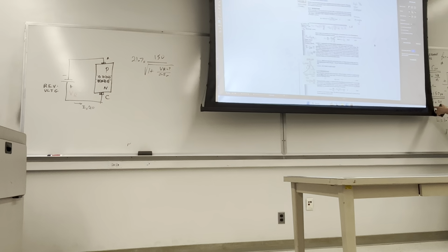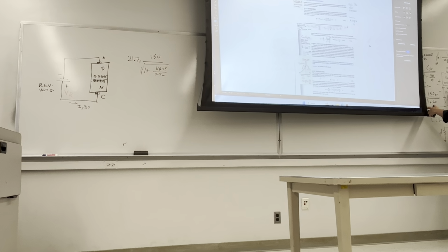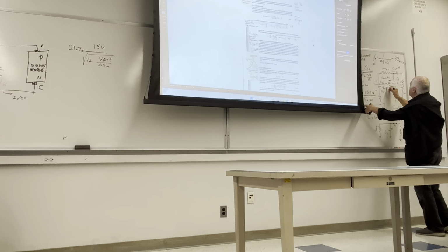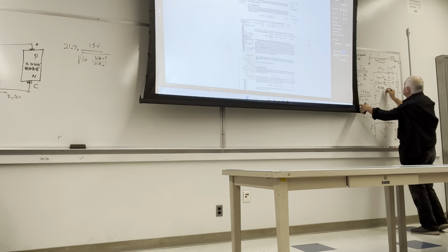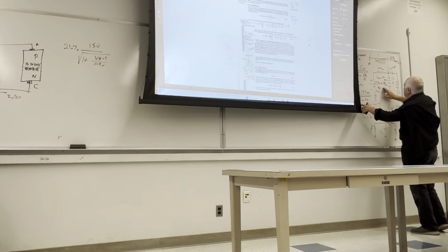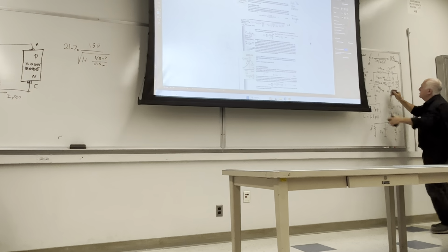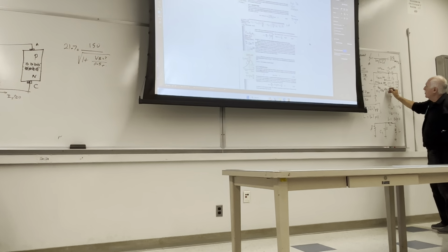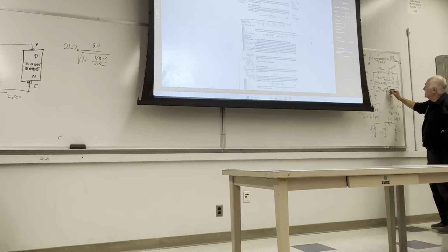So if it gets to VR of 23.4 volt, let's say 23 volt, we will hit the target 108 megahertz exactly.